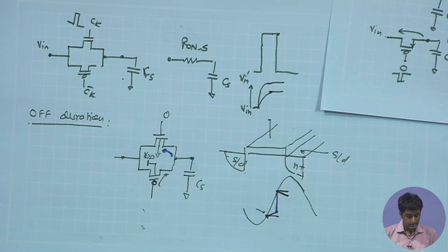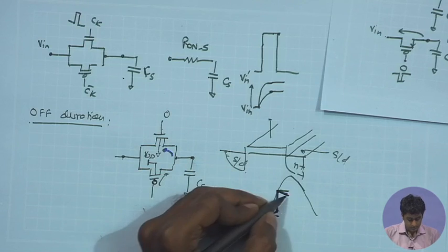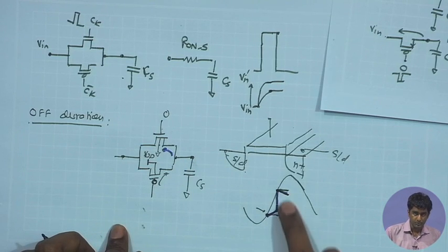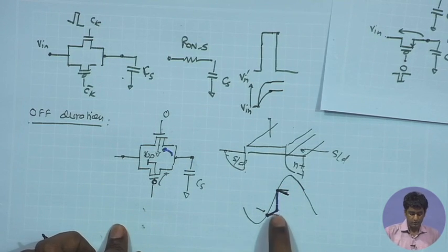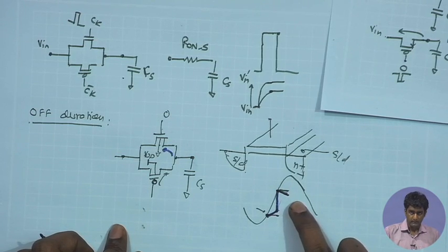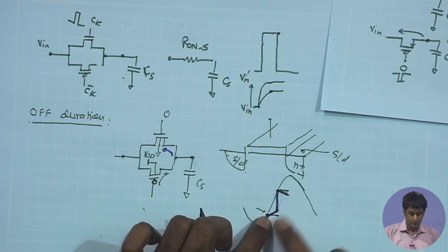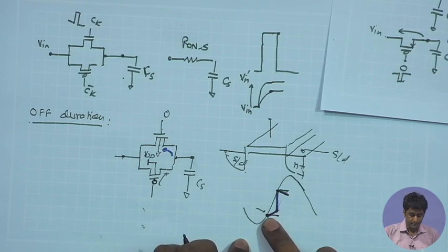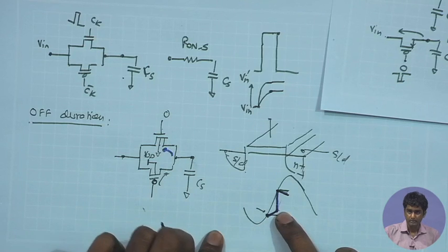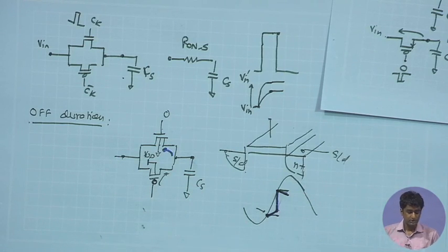If the junction leakage current is larger, the droop will be larger. So, the dark curve over here shows the actual waveform we will be getting. When you are going towards higher signal level, the sampled voltage can droop and deviate from the actual signal, whereas when you are going towards a lower signal level, the sampled signal stored on the capacitor can show a little bit of increase. This is true when your junction leakage is a dominant component.